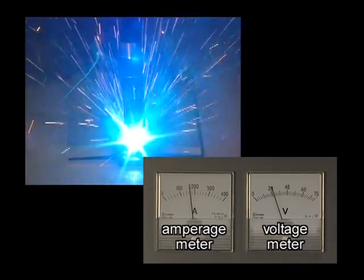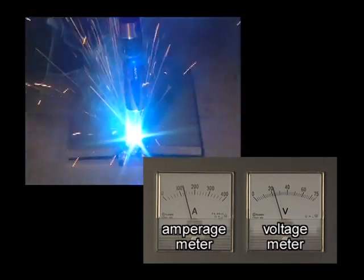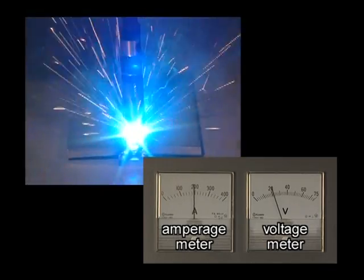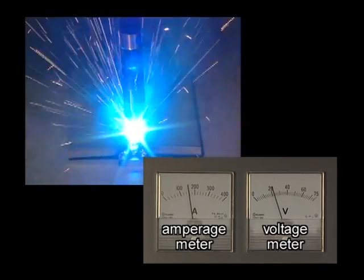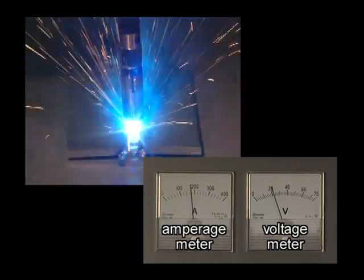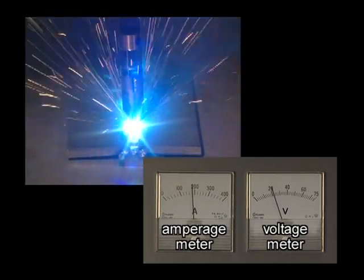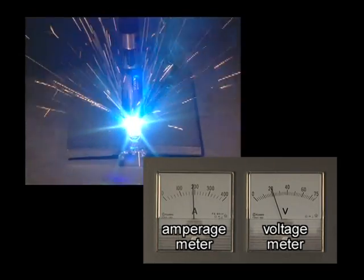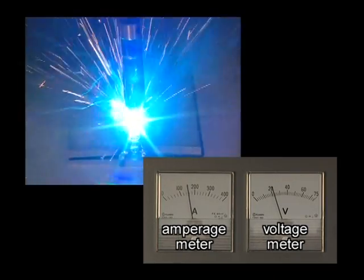In this way, moving the torch in and out causes undesirable welding results due to the changes in amperage, arc instability, and wire deposition rate. One of the most important things to remember when handling the torch is to keep the torch tip height constant while welding.